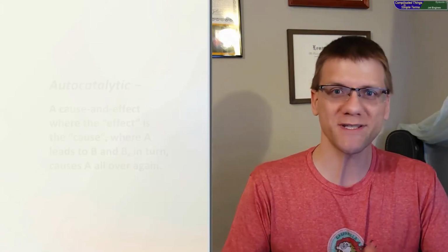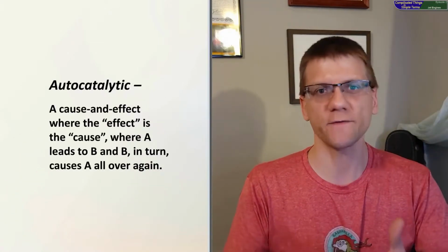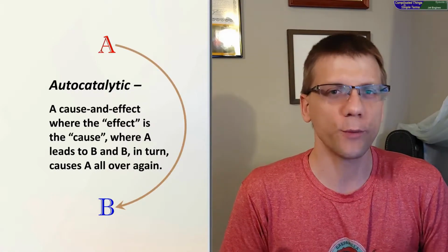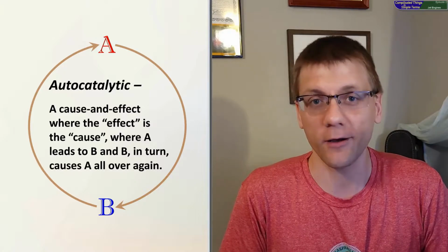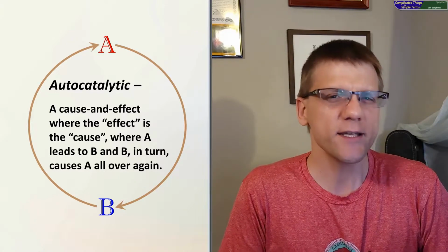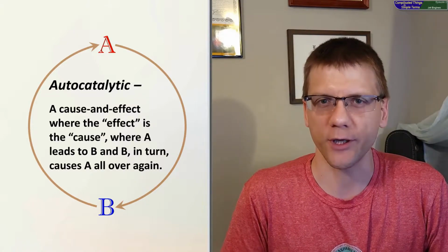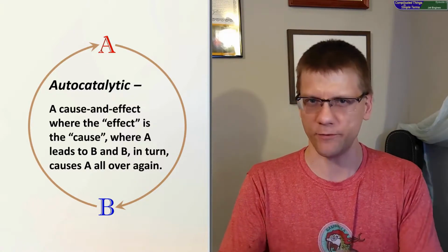This single spool setup is autocatalytic. That means it's self-sustaining. And that's one of the things that makes jet engines so reliable. The other thing that's cool about the autocatalytic nature of a jet engine is that it doesn't need spark plugs. So in your car, for example, in an internal combustion engine, you have to have things timed very precisely. There are cylinders that go up and down, and you only want a spark to ignite the compressed mix of air and gasoline, in the case of a car engine, when it's under maximum compression.